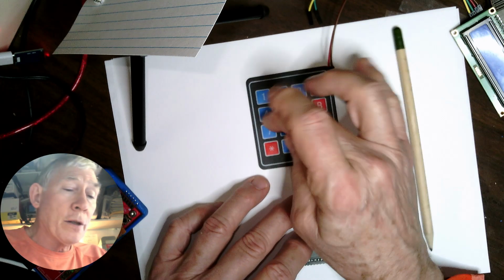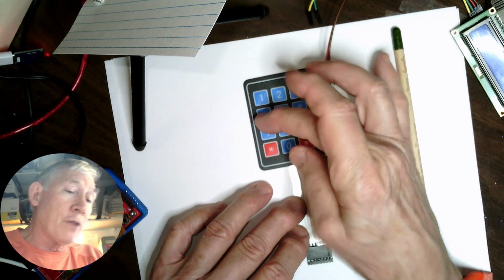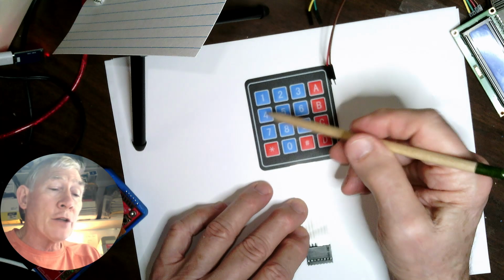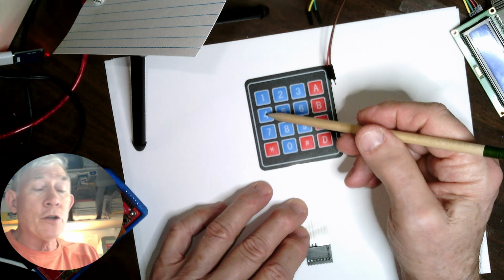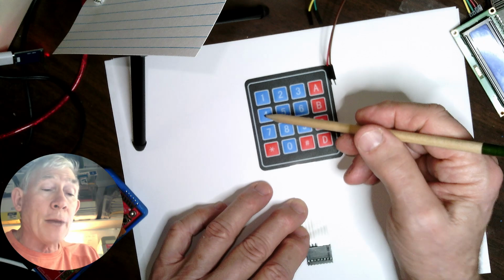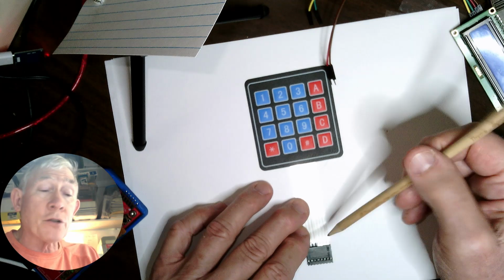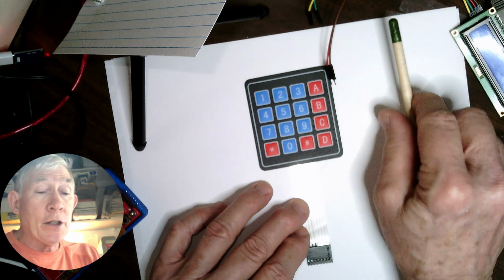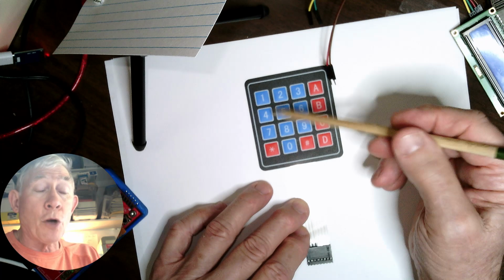And when you short a button, the top to the bottom, in the case of the 4, you're connecting row 1 to column 0, and your algorithm has to be able to program the microprocessor to detect that. And the way you have to do it, you have to detect both the row and the column.